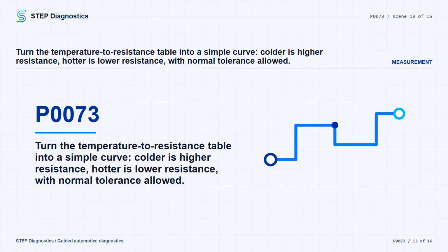When checking the sensor itself, remember the actual resistance can vary plus or minus 10% from the values in the table. If a temperature table is available, move the switch to adjust, connect an ohmmeter to the test leads, dial the tool to a resistance value in the table, connect both leads to the temperature sensor harness connector with the ignition on, and watch the scan tool for the proper reading. Use the tool to vary resistance while watching the temperature or voltage signal.